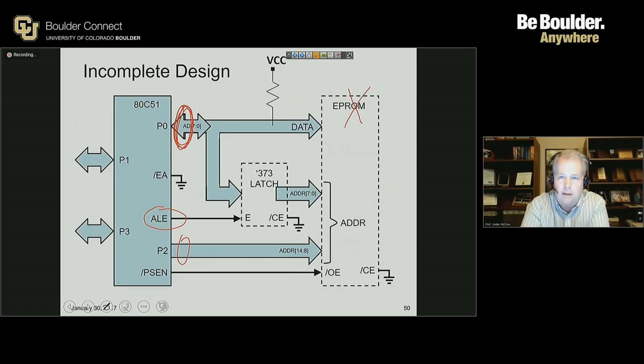Well, what is the next thing that happens in the state machine of the processor? After it reads from address 0, it increments the program counter, and what's the next fetch it does? Address 1. So it emits a 1, and then it reads back in the value. And what do you think it reads back in when it had just previously written the address 1 out? A 1. So now you can see that there's a situation where just because the processor is using its state machine, it's outputting something and then reading it back in.